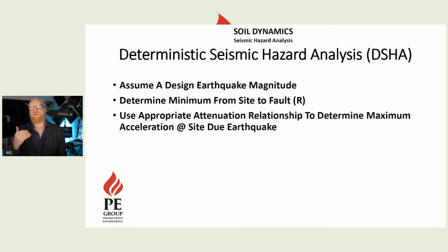Okay? Now, the basic idea of deterministic, it just means that it does not include the probability of that earthquake happening, does not include any kind of statistical data. So it's deterministic. It just gives you a maximum acceleration. It says for this site, this is the maximum acceleration that your single degree of freedom structure with a particular period is going to experience. It doesn't tell you the probability that it will experience that. That is the probabilistic seismic hazard analysis, which we'll talk about in the next video. But the idea is still the same. One just gives you, here is for a given magnitude and some certain other parameters for this site. Well, here is the acceleration you're going to experience.